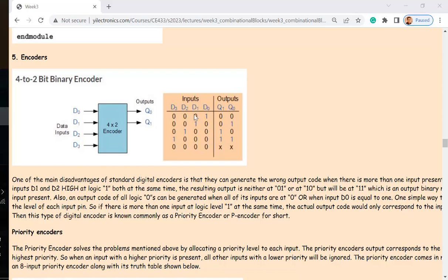However, the decoder can output a different pattern of binary numbers. It can be 1, 0, 0, 1, it doesn't matter. You can design whatever you want. But the usual definition of the decoder is 0, 0 and you just get a 1 turned on. So turning on D0, you assume that's the LED over there, then turning on D1 for the next one. So the encoder is the inverse of the decoder. The encoder takes these outputs of the decoder as the input, and the output is a 2-bit binary number.